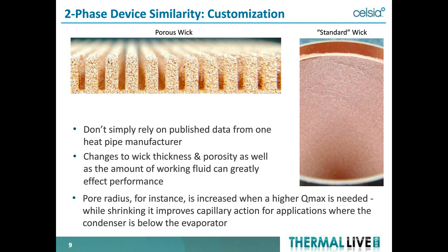It's just like designing a car for a particular application. If you want to go fast or if you want to go off-road, you do different things. You can change the wick thickness, you can change the wick porosity, you can change the working fluid. So a lot of things you could tweak to match the performance of these devices to the requirement of the application. So that's the key takeaway.